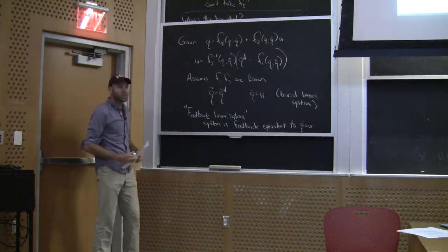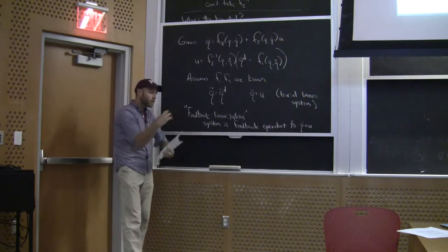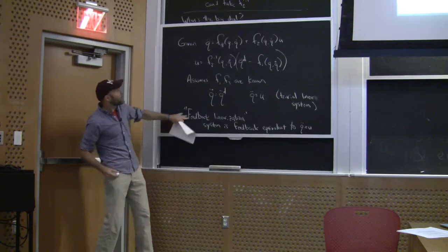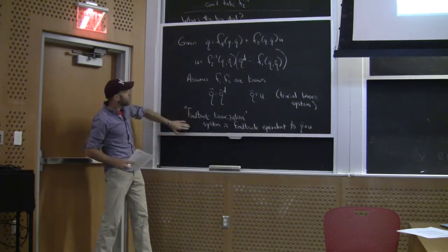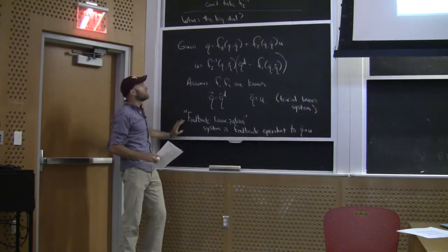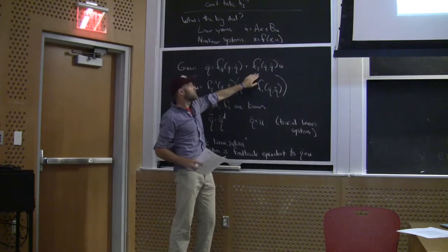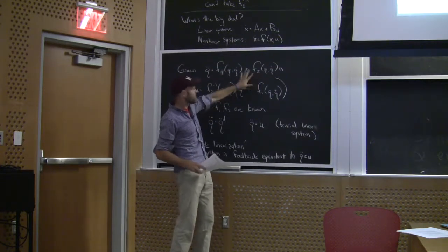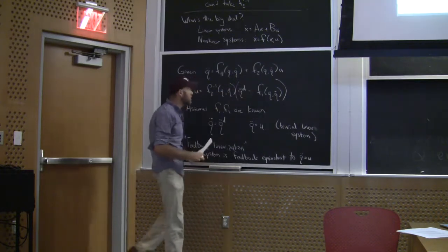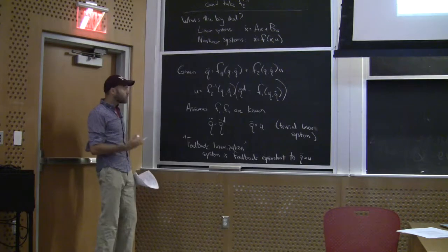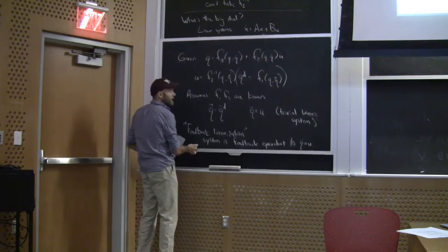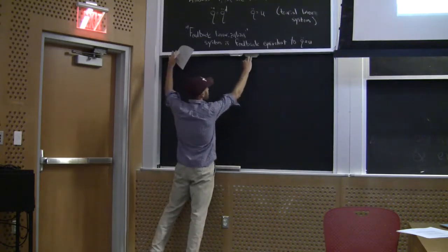Okay. So, long story short, let me wait and tell that story with the manipulator equations. There are other things that can break taking this inverse, that can break feedback linearization. Having F2 lack rank is one of the simple ways to do that. If F2 is not full rank, we'll show you examples of how that plays out. You can also break the ability to do feedback linearization by having other types of constraints in the system.